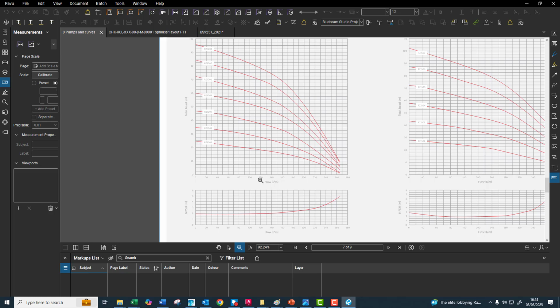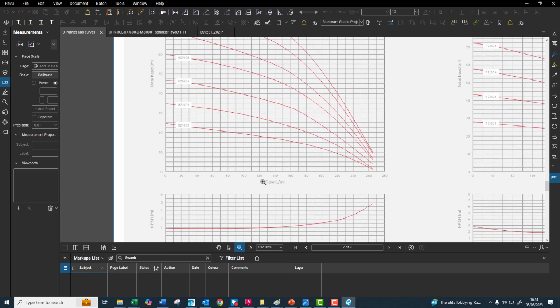So we're around 120. Oh, we're getting close now. So there is 120. Okay, we're under 116, but it's close enough. 120. We move up, and now that will only give us 38 metres head. I think that's a 32 force. No, 32 and a half, 35. That will only give us 37 and a half metres head.